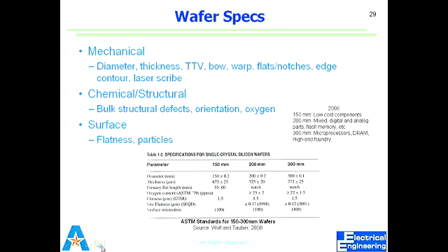A chuck is a round platform that has grooves in it, and we apply vacuum through those grooves. Once you put the wafer on top of that chuck, the vacuum sucks the wafer down, so it's very hard to move that wafer. Why do you want to do that? We rotate it at thousands of RPMs to do some processing, so it has to be very flat.